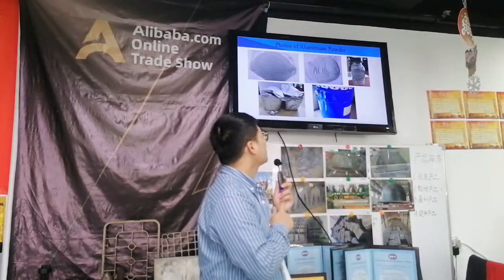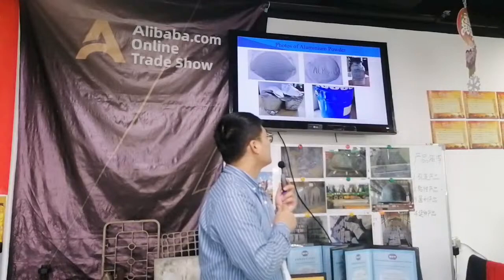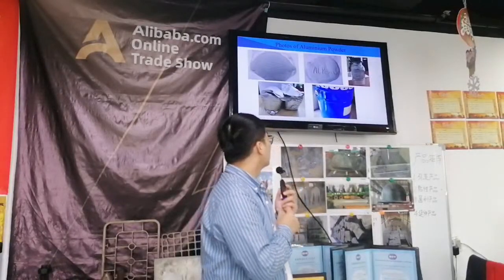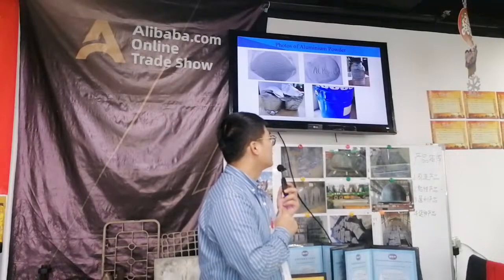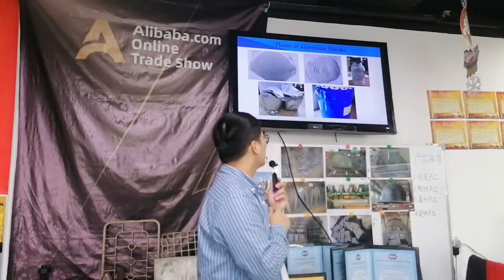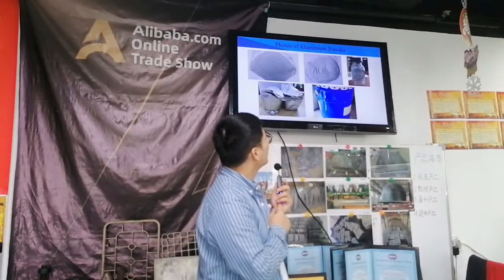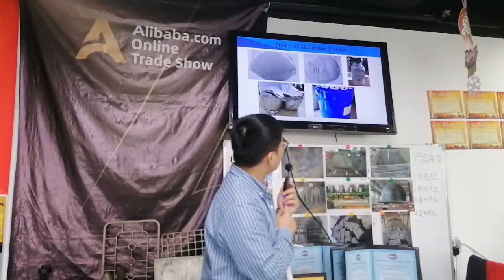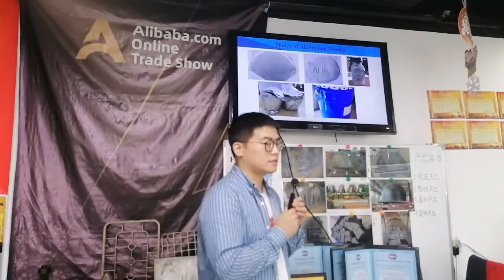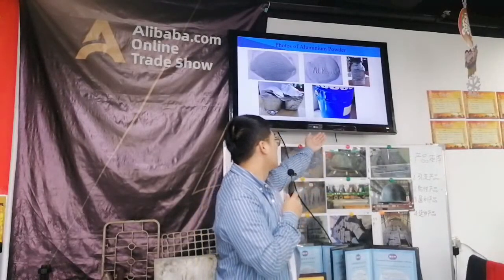Usually, the aluminum powders are packaged in protective gas-limited plastic bags or aluminum bags. And it is also like the nickel powders packaged in metal drums, as you see in the fifth picture.